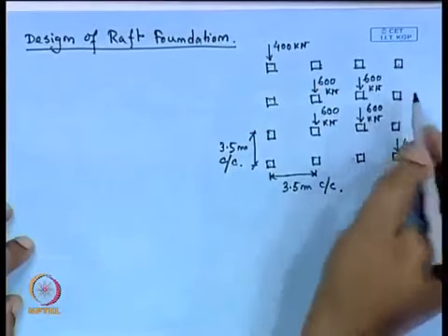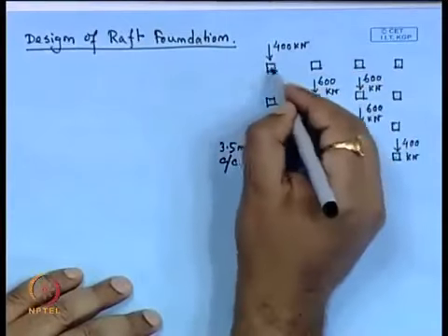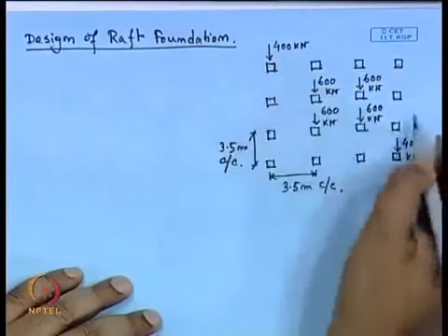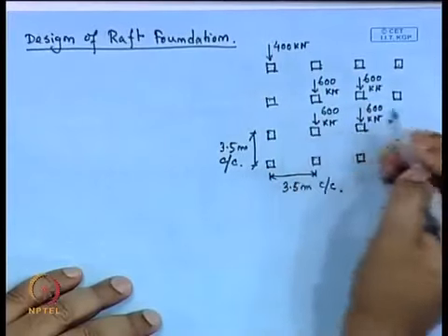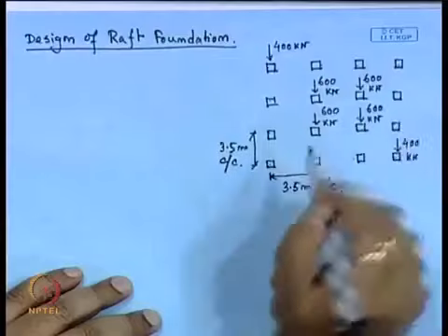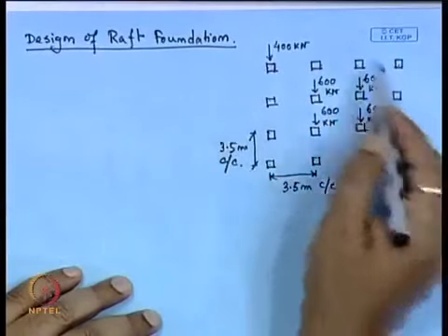Now, as we design, we will use the raft foundation, for it is observed that the raft foundation is a suitable foundation as the bearing capacity of the soil is very low. So, that means we will consider the raft foundation. That will be considered for the total area of this structure.